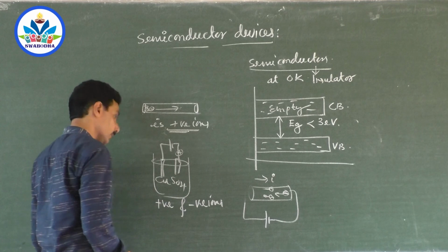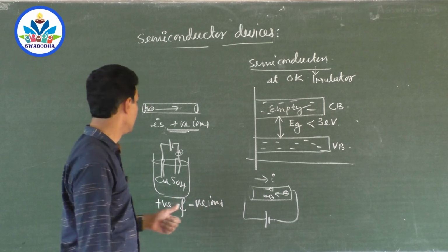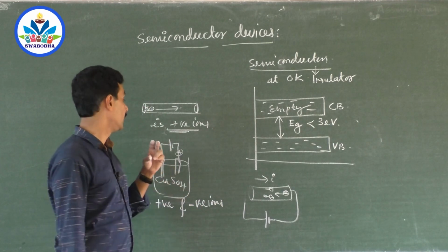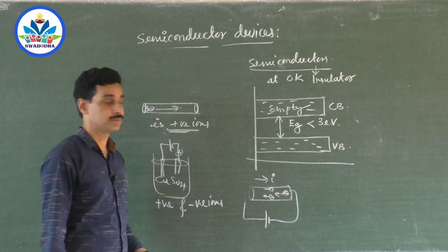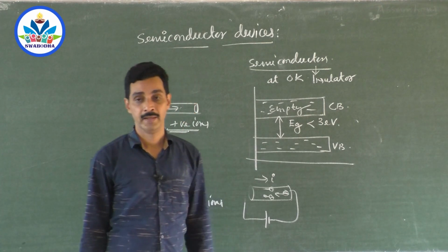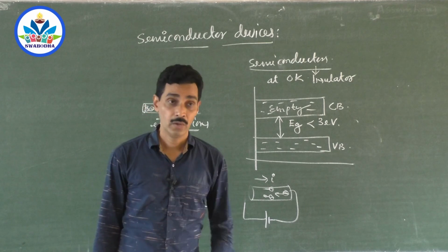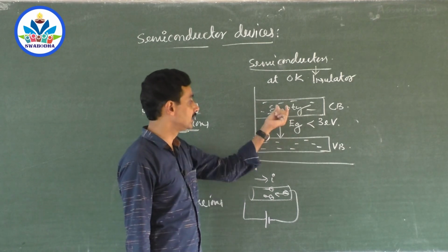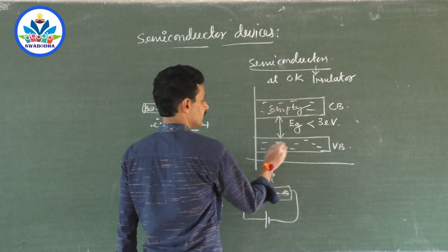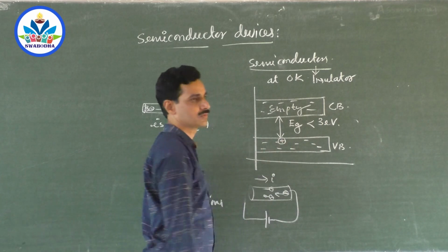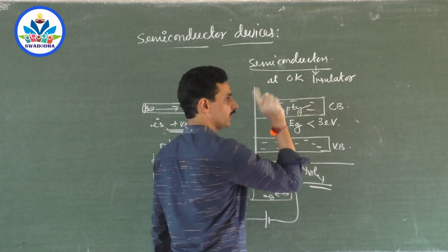Sir, what about semiconductors? So in conductors, free electrons; in discharge tubes, positive ions and electrons; here, positive and negative ions. What about in a semiconductor? Electrons as well as some positive charges called holes. What are holes? Now, when one electron goes to the conduction band, this electron has left this place. So here we have a vacancy, that is called a hole. Holes are found in the valence band. Free electrons are found in the conduction band.